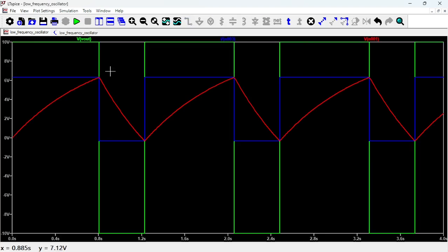And that's what you see here. I think it might be below 0 actually. So that's where we are here and here. The capacitor is discharging, and as soon as it goes below that minus epsilon volt, the op-amp is going to switch again, and it's going to go into its high saturation.